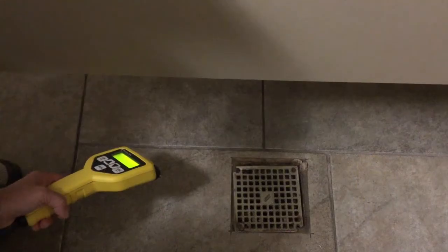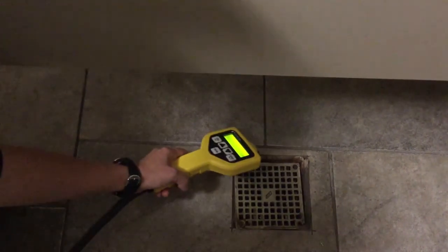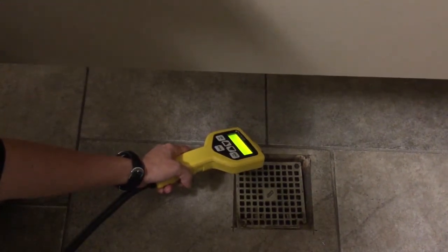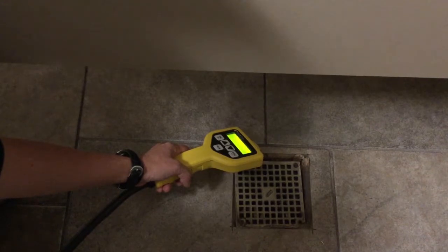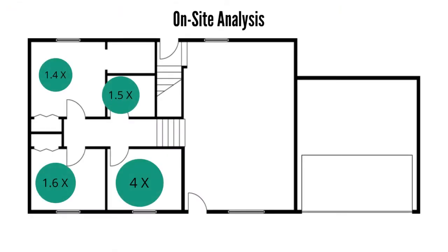Alternatively, when vapor intrusion is occurring in the building, using the instrument we'll commonly find that a specific crack in the foundation or a floor drain is an important pathway for the vapors entering the building. So this confirms that vapor intrusion is occurring, and it also gives us a head start in figuring out a way to remedy the problem to prevent the vapors from coming into the building. So that's the basic way to use this on-site instrument for diagnosing vapor intrusion issues.